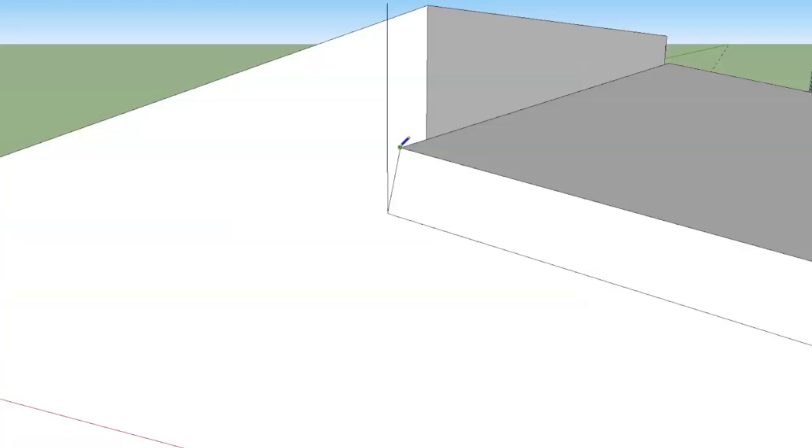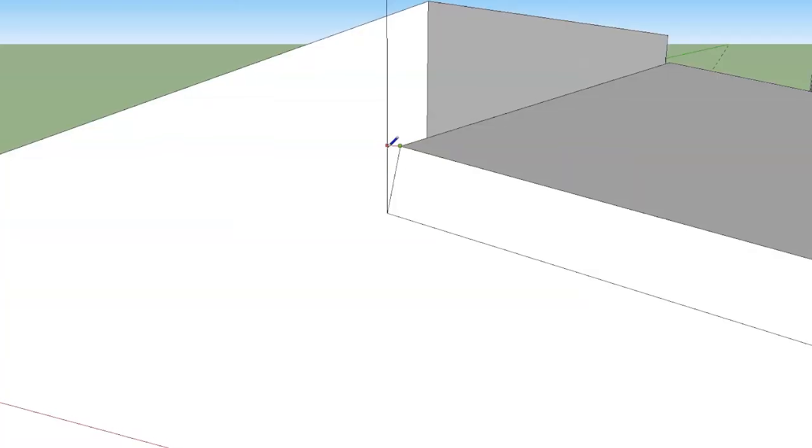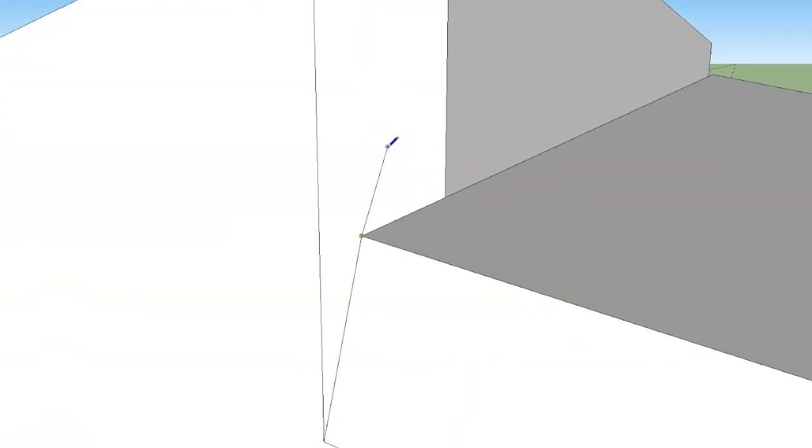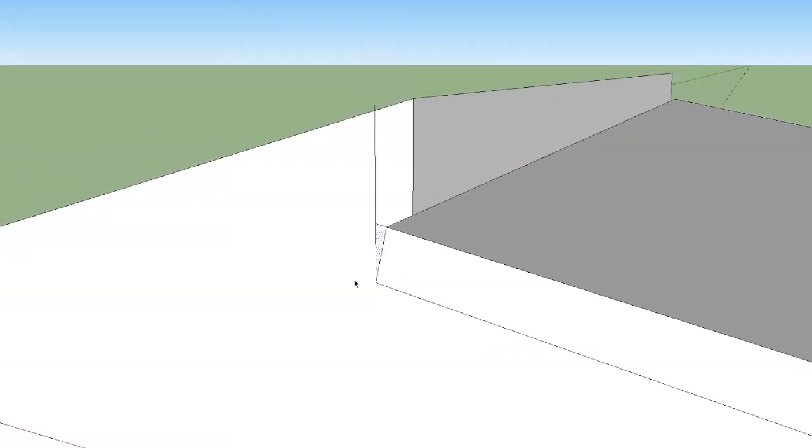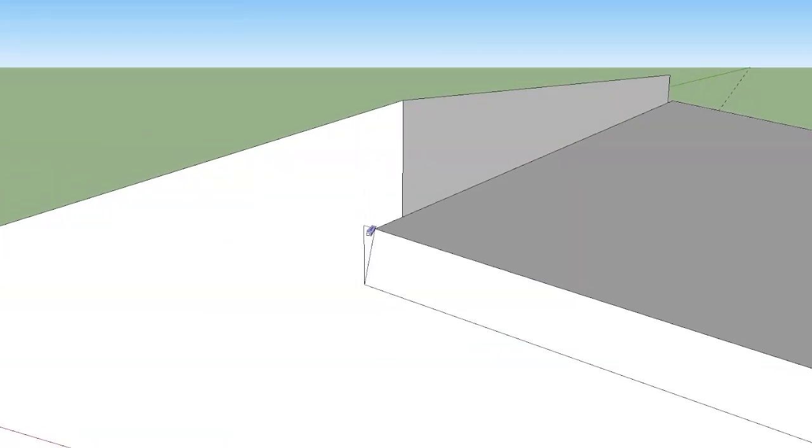Now, even though our axis tool is set to be rather regular horizontal axis, if we click here and draw a line out, there's the red axis, right? But if we go up, I'm going to zoom in a little bit here. Right, there's the red axis, that's flat. But if we go up a little bit, it snaps to a pink line, which is parallel with the line coming from back here. So it continues the roof line for us, which is really, really handy. And that has created a face for us right there. We'll delete that extra line. Take the push-pull tool and push it back.